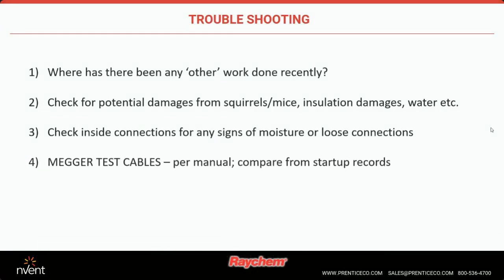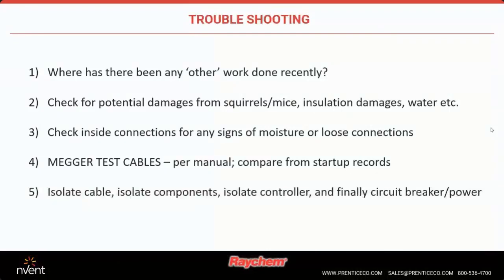And then again, you go back to, let's test the cable out. If you have done your job on the startup, you should have a record of what the installation numbers look like. So now you can compare that record and say, okay, how does this Megger test now compare? Is it greatly different? Is it the same or similar? Is there a problem? And you can go from there.